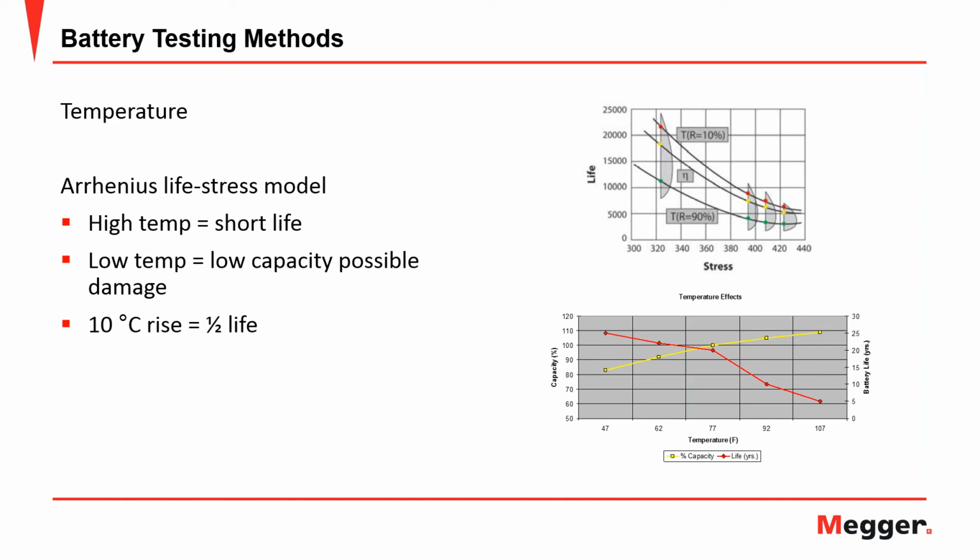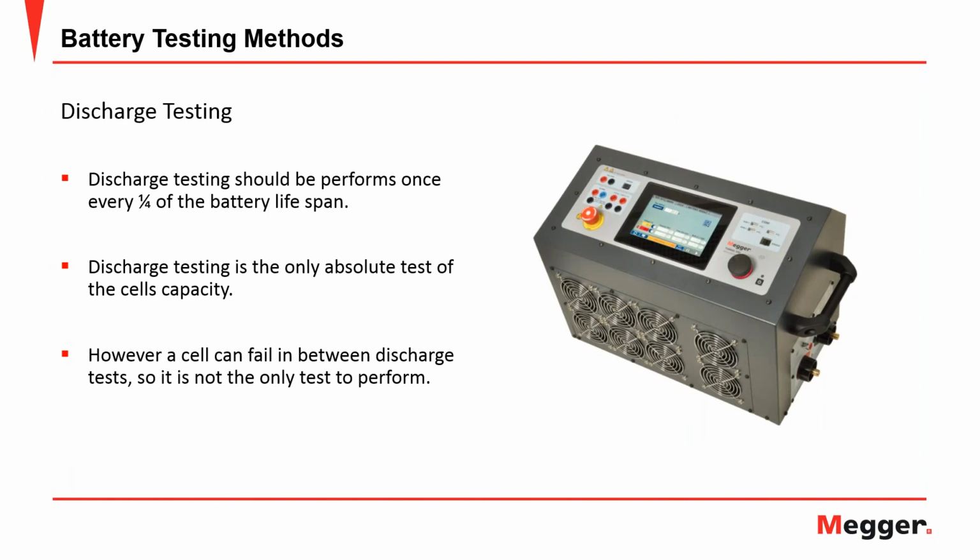Discharge testing. This is the only test that will actually tell you the actual capacity of the battery, and it should be done on a quarterly basis, as Volney had already discussed.